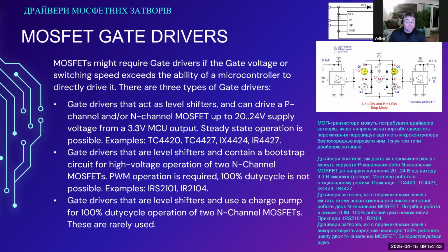MOSFET gate drivers. MOSFETs might require gate drivers if the gate voltage or switching speed exceeds the ability of the microcontroller to directly drive it. For most microcontrollers and for most high power applications, that will be the case. You need a gate driver.